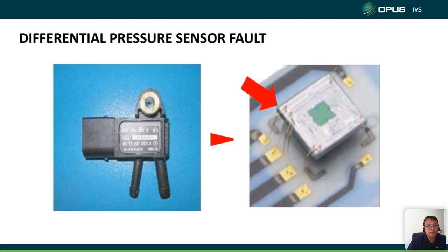Bear in mind also, in some cases, it's only the vacuum hoses which are not fitted properly. If you can notice, there are two types of hoses there, one small and one big. And I always recommend don't use that screw type hose clamp, because in some cases, if you overtighten that one, you either damage the hose or you damage this fitting. It's only made of plastic.